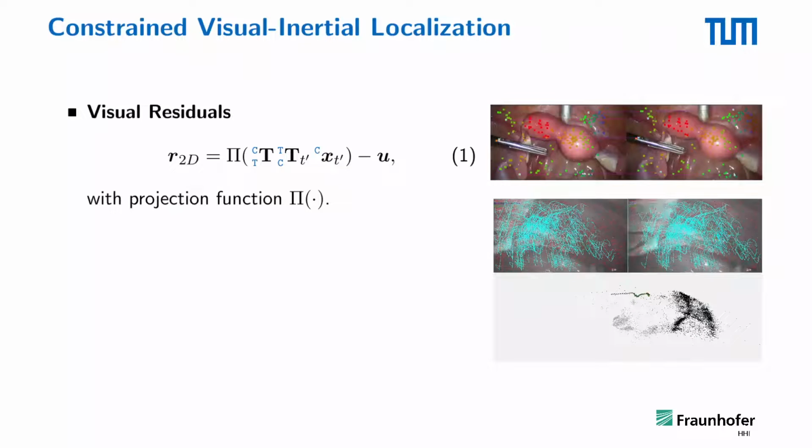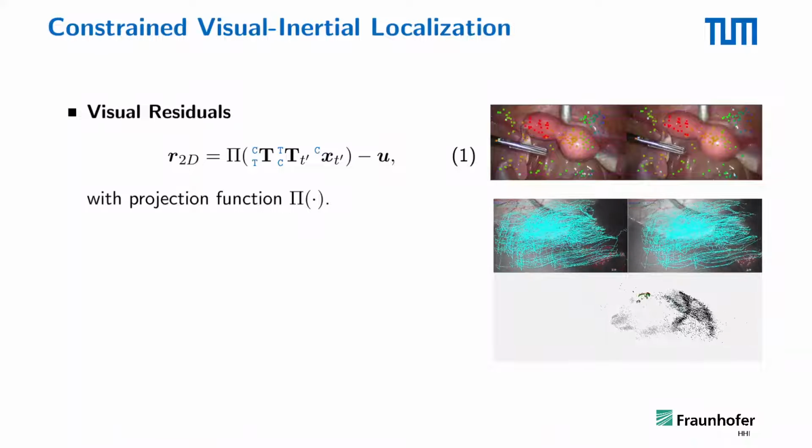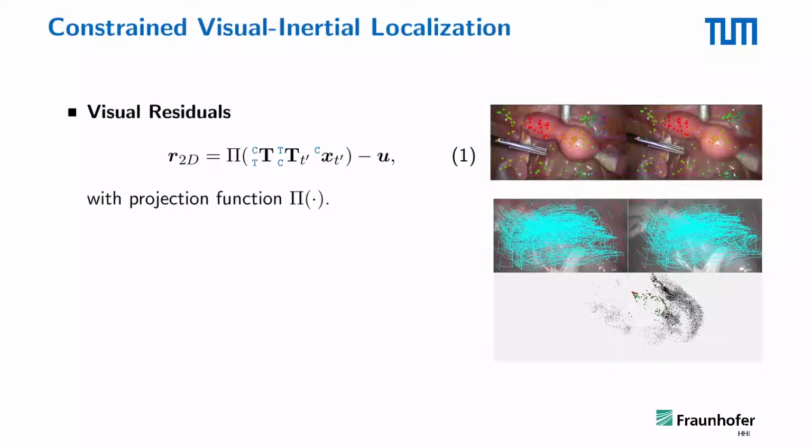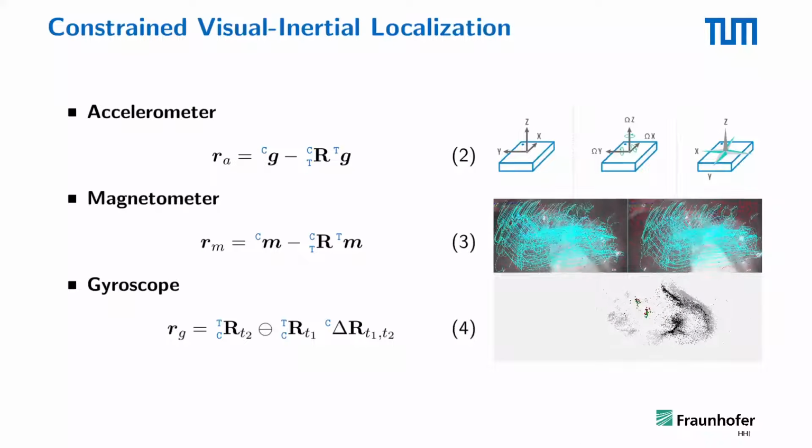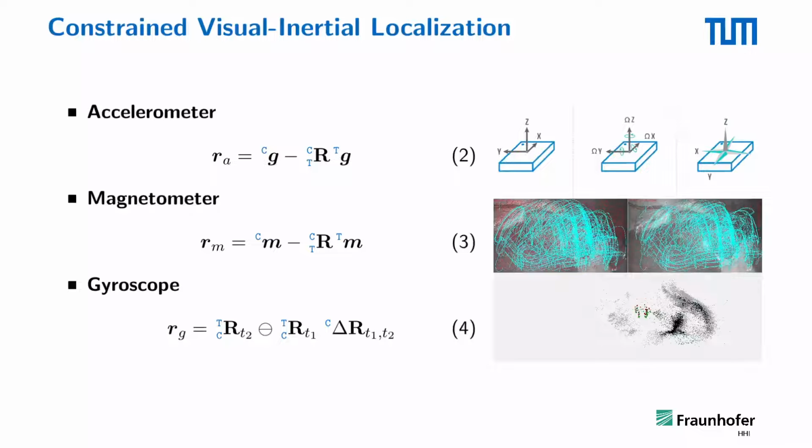We, however, tackle applications where the image content is moving or the image quality is so low that the algorithm loses tracking. Therefore, additional information needs to be taken into account. The inertial measurement unit gives us 3 residuals: 2 static directions we can align the rotation part with, as well as a rotation update based on angular velocities.